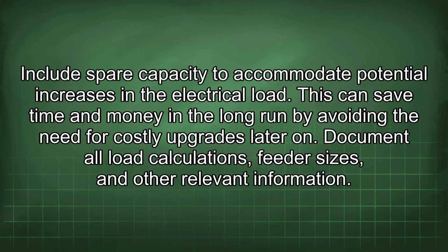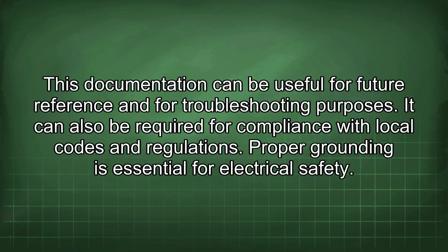Document all load calculations, feeder sizes, and other relevant information. This documentation can be useful for future reference and for troubleshooting purposes. It can also be required for compliance with local codes and regulations.